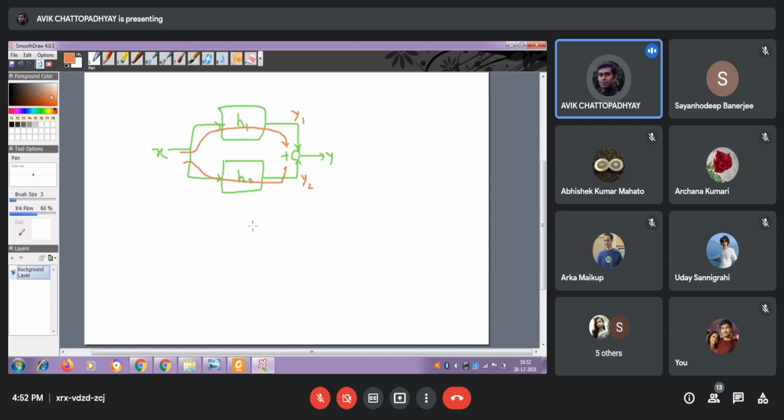So here, I can realize that this is equivalent to applying the distributive property, the same property we just saw for convolution. Because ultimately, when dealing with LTI systems, we do not apply anything other than convolution. So in whatever way you argue, you will reach the conclusion that all the properties applicable for convolution are equally applicable for the LTI system.